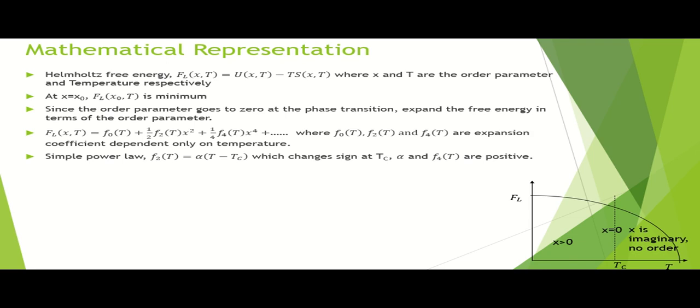And when you get very close to the phase transition temperature, this linear dependence is not valid, because there are lots of fluctuations in the density of the material during the phase transition. In the solid to liquid phase transition, for example, the density changes suddenly, and therefore the fluctuations in the density are too large to assume a linear dependence.